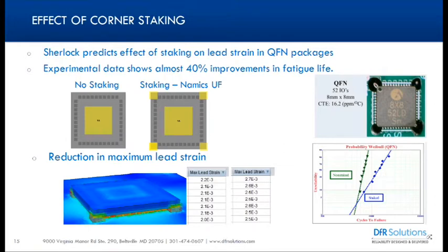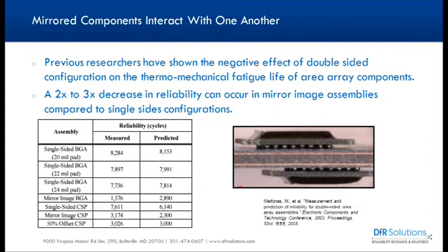Let's talk a little bit about mirrored components. So essentially what happens with underfill, there's not much you can do if you're not the person who determines if the underfill goes in. If you have any kind of input as to what goes onto the underfill or to the manufacturing process, then you should choose the right kind of underfill and just do the simulations or do the test in order to determine that your underfill is okay. For mirrored components, it's a little bit different because this, you absolutely, as a board designer, have the ability to change it.